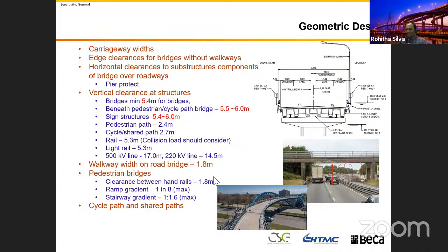Another thing, when you are designing a bridge, you need the road width and the carriageway width to match your geometric design. Your highway designers will give you this. Your road authorities will also inform you of the minimum lane width, which for the highway is 3.5 meters. So we need a 2-lane highway, and then the width depends on speed and the geometric design, and the highway designers will come up with the right dimension. You need to fit the bridge to those dimensions.